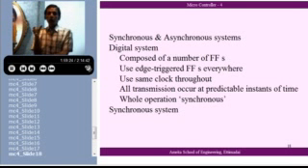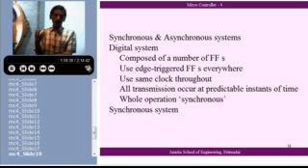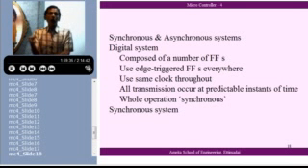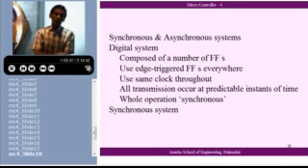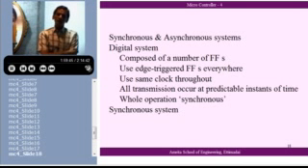Apparently, I am losing out on something. I am not able to cash in on the speed of the system. I give a set of logic inputs, the output has taken new values, but I have to wait for the next clock input to come and then take the new value. Apparently there's a slowing down. But that is not right. It is something like this.